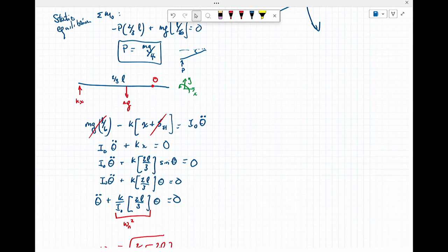So you can do it so that you reference everything to this position. But normally what you expect is that a rod will go down because of static equilibrium. And what you want is the spring displacement. And so that's your theta, that's your displacement in the spring, and that's why you're looking at sine theta. And the weird part of all of this is, as far as you're concerned, and as far as I'm concerned, this distance and this distance are the same. It's very, very small displacements.